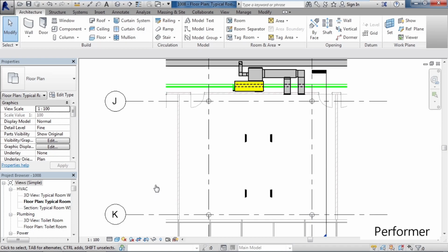In this lesson, we'll cover duct systems. So you may ask, well, what is a duct system? What does a duct system contain? Well, a duct system contains all the elements within that physical system. So it could be the component that supplies the air to the actual system. It could be the actual diffusers or terminals at the end of the system that the air comes out of. And it could be anything in between these elements. So the actual duct work, duct accessories, and duct fittings.